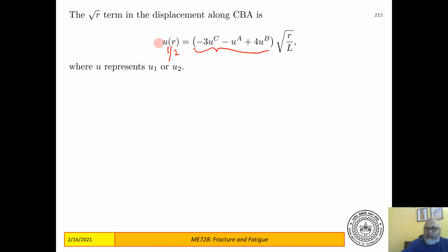And now if you have got u1, we have an expression from the Williams solution for the crack tip opening. So if this is your x1 and this is your x2, we know that the crack tip opening delta is, you have u1 given as K1 root 2 pi r divided by 4 mu pi, I think, u1 hat theta, and u2 given by a similar expression.